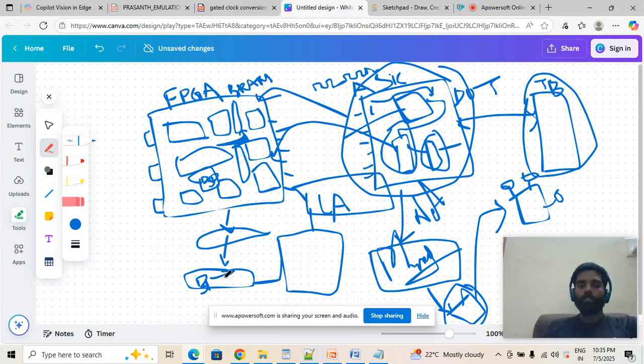Once you get the bitstream file, you will go to your FPGA. This makes real hardware, FPGA real hardware, okay? And I'm going to put it on my FPGA board. Once I put it on my FPGA board, I can get the visibility into my debugging environment. Like a simulation, I can get the visibility in the ILA platform. It's called the logic analyzer platform.